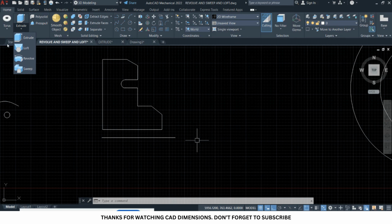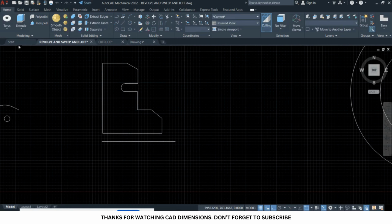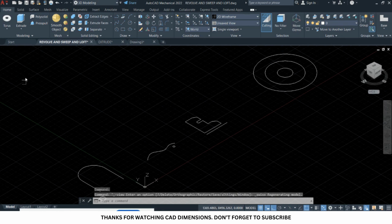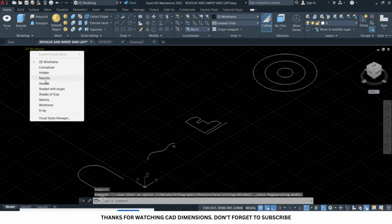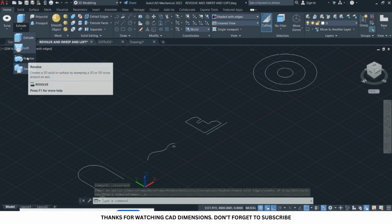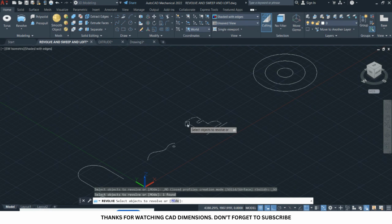Okay. So before that, let me change the view. Let me change the view to southwest isometric. Let me also change to shaded with edges. Okay. So now I come to the revolve tool and the command tells me to select the object I want to revolve. So this is it.